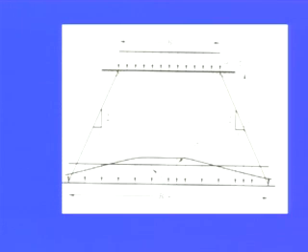In the case of strip footing it is 1, in the case of rectangular footing it is length L, and in the case of square footing this is width B. So, we distribute the total load, B into q into whatever is the dimension in the other direction, divided by B plus Z into 1 or the dimension in the other direction, depending upon the shape of the footing.